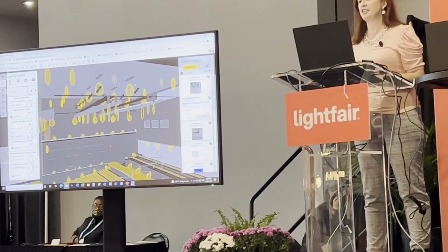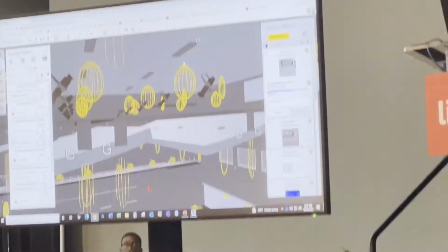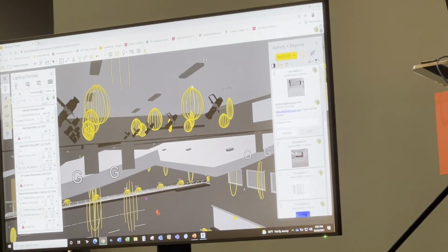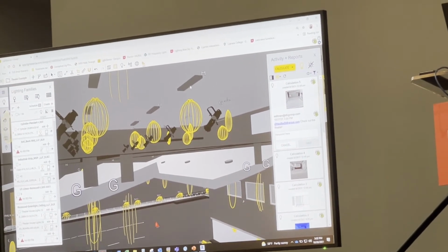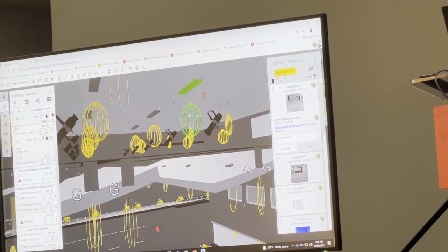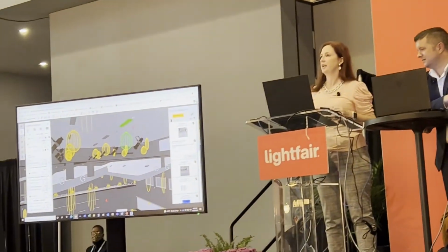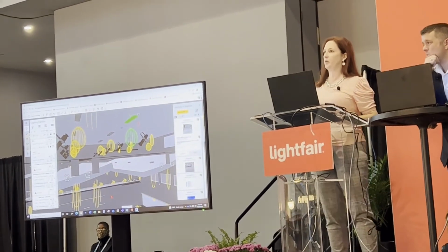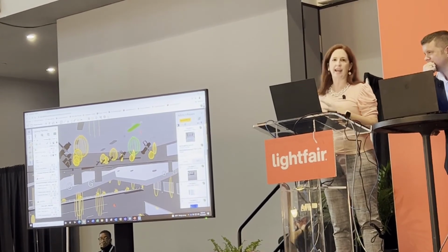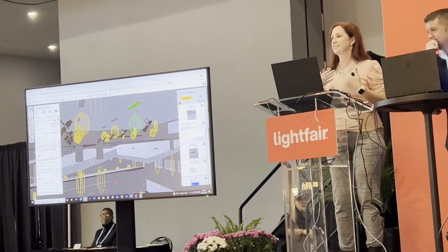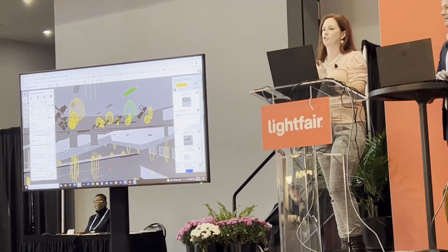So for instance, you can see how these photometrics are floating about a half a foot below. So you can select, well now if it lets me select it, there we go. So you can see how the geometry's up here, the photometrics down here. That was because that's how the family was in Revit. And I knew it was going to take like hours. I would have to get the BIM team on it, because I will admit, some of the ways that they constructed the families, I wouldn't know how to do it with all the constraints.